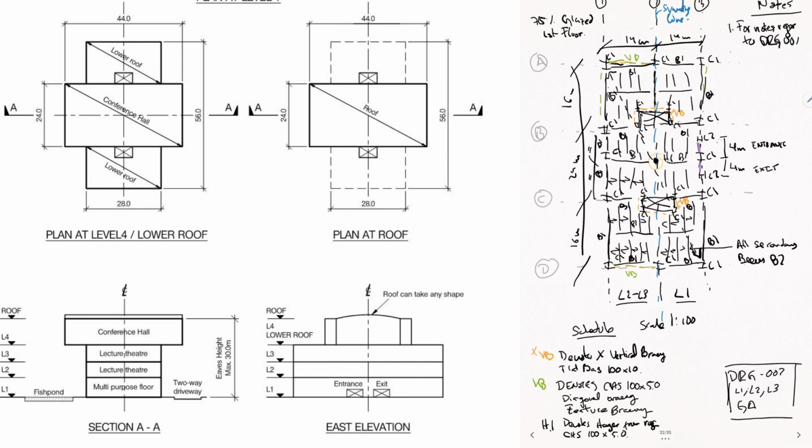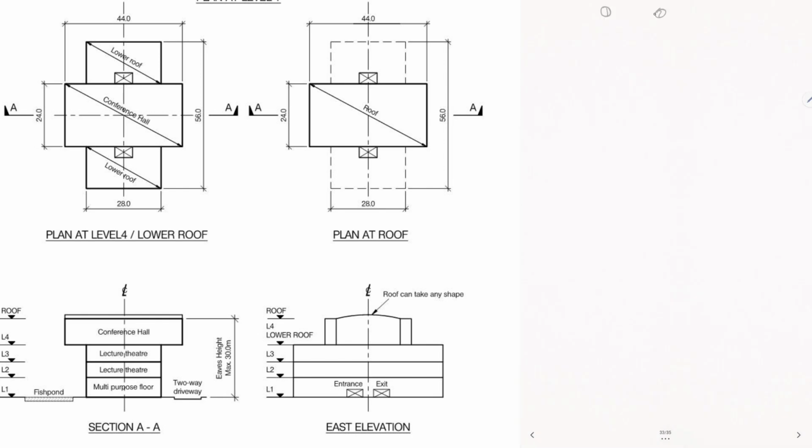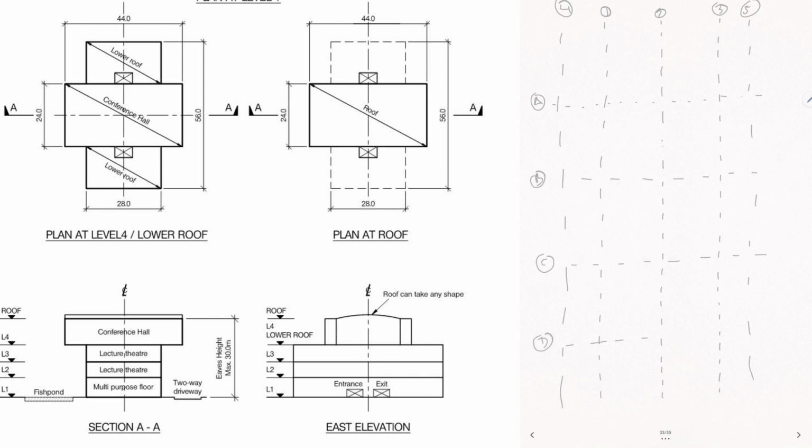Then the secondary beams were all sized by typical sizes. In the structural engineering pocketbook, for example, you can find typical sizes for when you're using a metal deck concrete composite slab. Then you have your primary beams and your secondary beams at closer centers, and there are guides in there of, well, this is your live load, this is your span. Just make sure you use those, because you don't need to really calculate the capacity of those beams because they are not the primary structural elements.